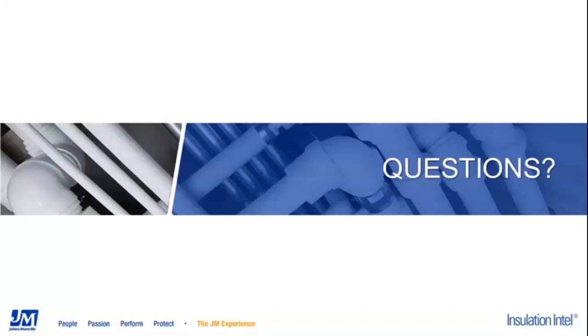All right, excellent. The next question, Meredith, is also for you. You're in the hot spot apparently, and that is, does JM offer color-matched caulk for the colored PVC jacket? So we don't offer color match caulk, but what you can use is our clear solvent weld adhesive. So that's going to basically blend in with the PVC, and that would be a great option for sealing up our PVC.